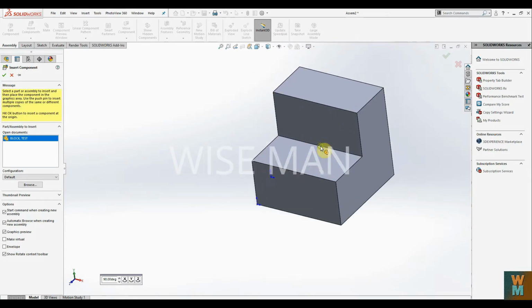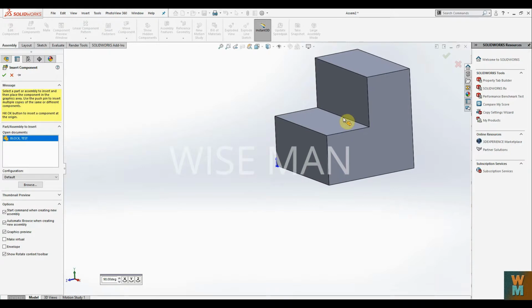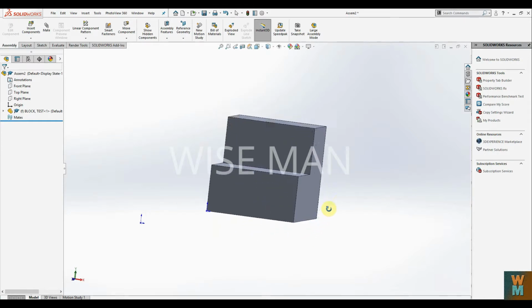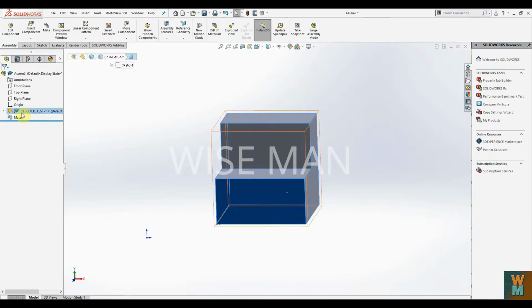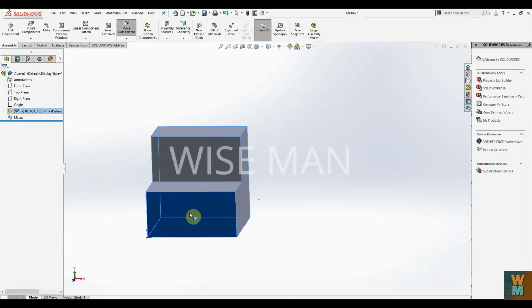put it, like you have to put it at the origin. The origin of this part drawing must be coincident with the origin of this assembly file. Now as you can see, this is not coincident. What you can do, you can move this drawing, but as you can see here, this is the F sign. It shows that it's fixed. So you can right click on this and click on float. So now you can move this part in the assembly file.